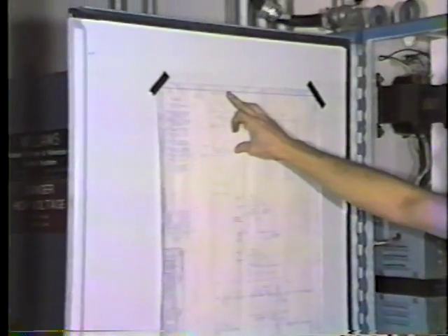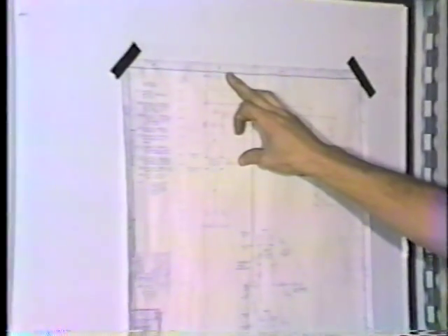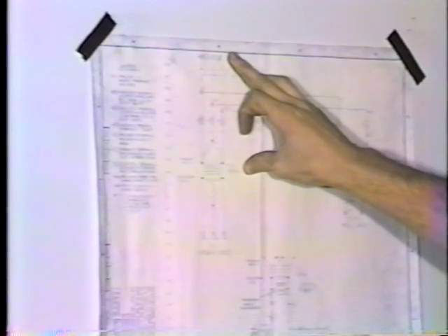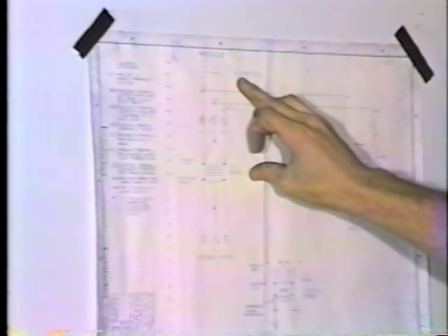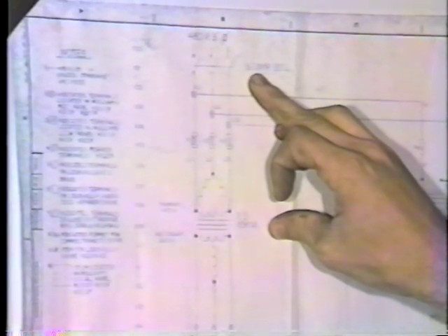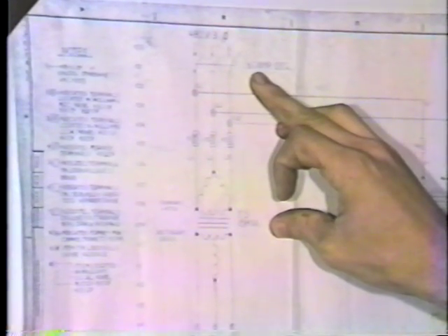We will now examine the electrical schematic for the pulverizers. Drawing number 102D 9956, page 1 of 11. I'm going to zoom up to you now. Okay, go ahead. Coming in with 480 volt 3-phase power into our disconnect. Terminal blocks 1L1, 1L2, and 1L3.